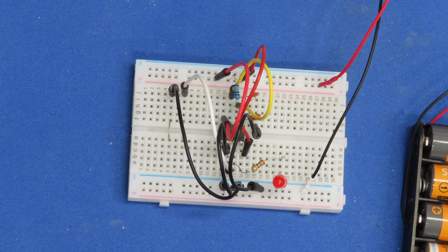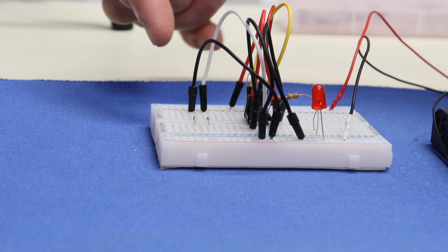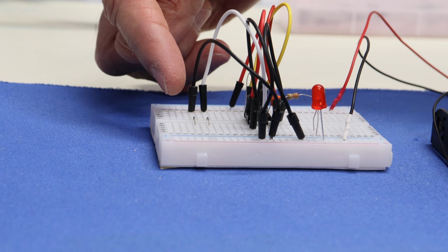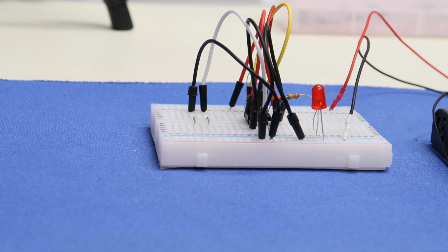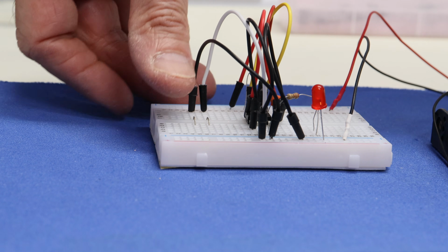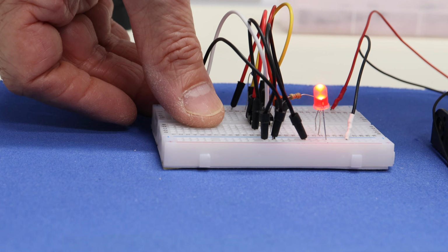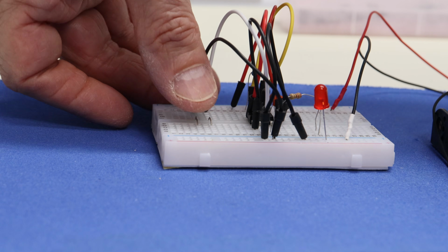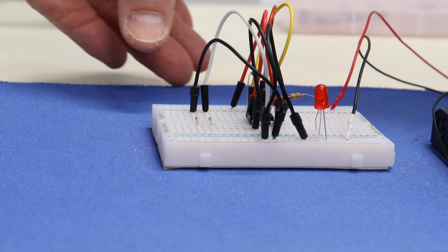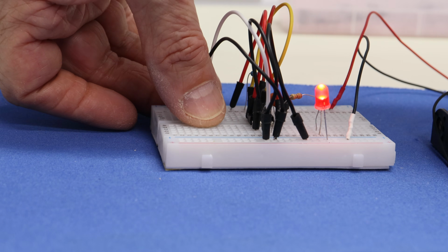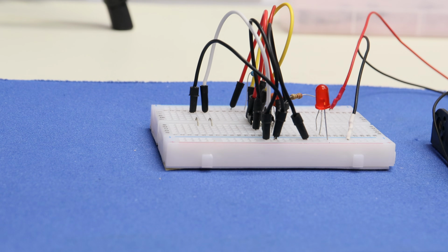So here's my touch switch wired up on a solderless breadboard, and for touch switch sensors, all I used was a couple of pieces of wire. You can see them back over here if you look carefully. They're on the breadboard, and when I touch these together, the LED should light up. So let's just do that. And the LED does indeed light up when I touch this. And so another very simple 555 demonstration.